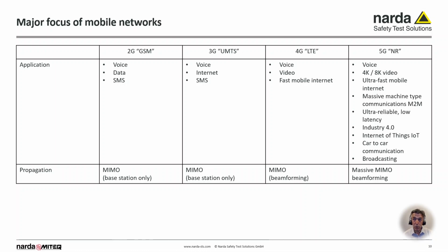Okay. So, and also a lot of operators went over to software-defined radios. So that means 4G base stations were possible to switch over to 5G services or dynamic spectrum sharing 4G and 5G within a 120 megahertz signal by just a software update of the base station. So the base station became more and more intelligent and much more flexible. So the rollout of 5G was in parts just a software update, so a rollout by mouse click.